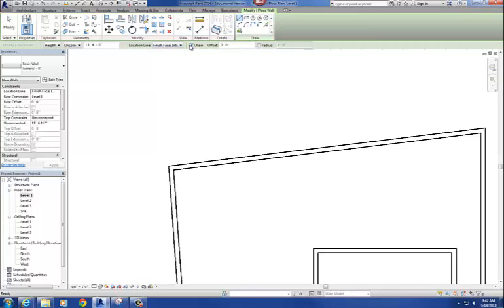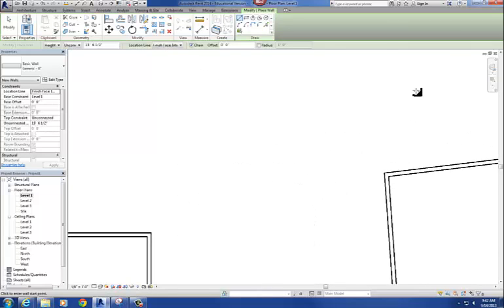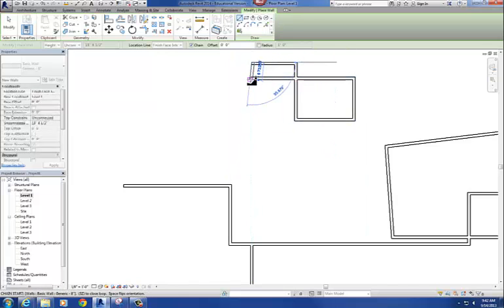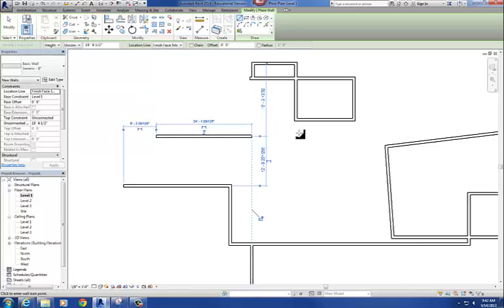The next one is chain. When the chain box is selected, it means I'm drawing a wall, and once I finish this wall, the next wall is ready to begin. I don't have to go back up and get to the same command. So if I'm drawing walls in series, with the chain selected, I'm just going from one wall to the next. As opposed to when it's unchecked, and I click a wall, and that command is finished. So that's the chain command.